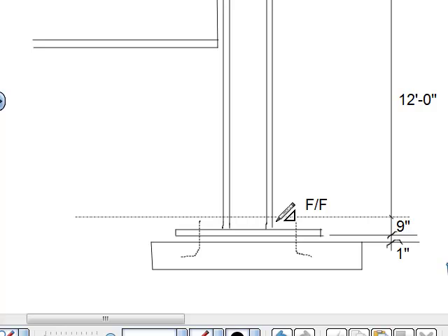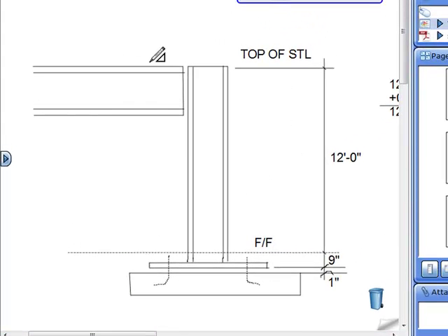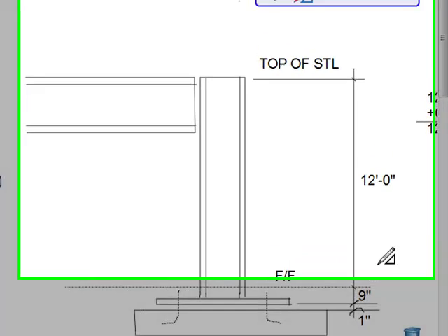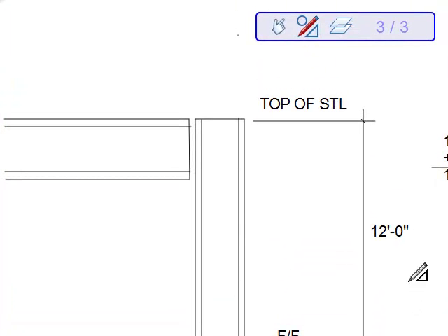So what they're saying is you have your top of steel, and that's what I was trying to draw here. Then you have your foundation down here with your anchor bolts, and you have the base plate right there, and then you have your finished floor. All that's going to be dimensioned on those engineered drawings. And if you look on page 116, you kind of see it. You can see that information given to you there on those sections. On 118, the drawing is a little bit better.